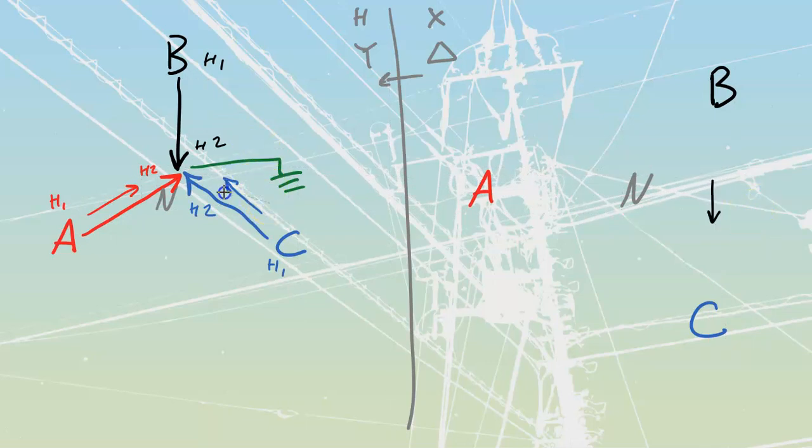We're going to go in and we'll grab another one. We'll grab this one here, the C winding, and I'm going to say, does it connect the line from A to B? Nope, it doesn't connect anything inside there. Is it lined up with A to C? You bet it is. And we're going to do the same with my A. The only place left, this one is taken, this one is taken, the only place left is A to B. And if I take a look, it definitely does align with that.